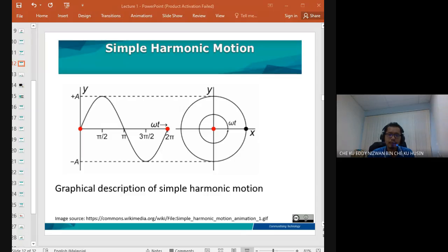For displacement, if you measure at low frequency, meaning the motion is very slow, then the best sensor is one that measures displacement. However, when you go to high frequency, the error increases. It's vice versa for acceleration.